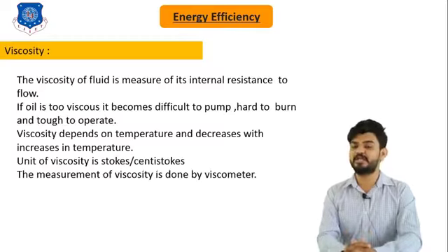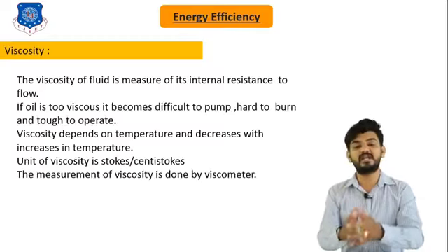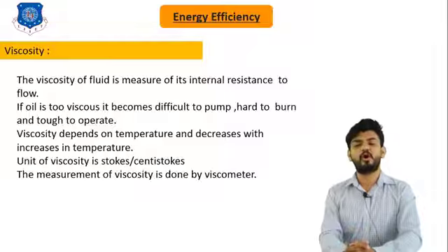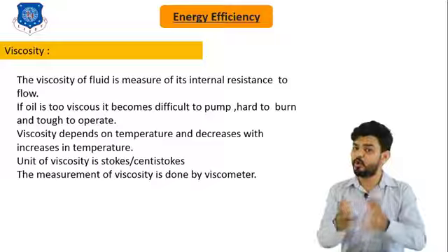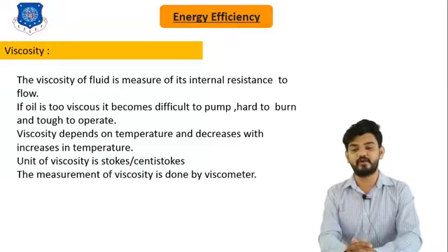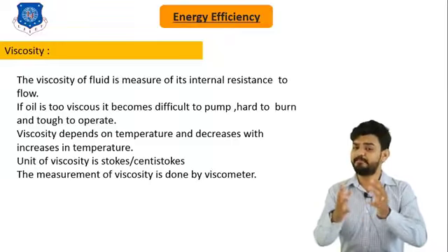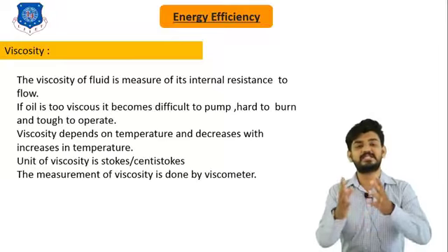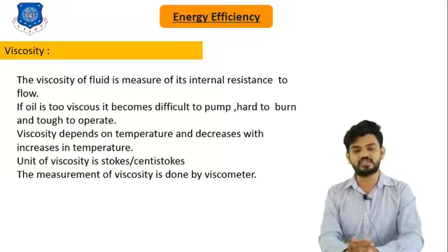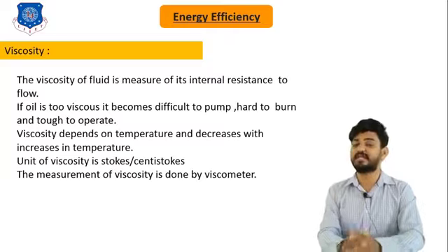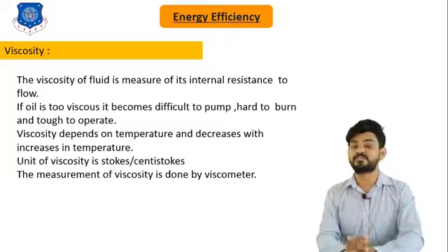Now let's move to the next property of fuel, and that is viscosity. Viscosity of a fuel is a measure of its internal resistance to flow. If oil is too viscous, it becomes difficult to pump and ultimately tough to operate with this kind of fuel. So low viscosity fuels are always preferred. The viscosity also depends on the temperature. As the temperature increases, viscosity decreases. The unit of viscosity is stokes or centistokes. The measurement of viscosity can be done by different viscometers.